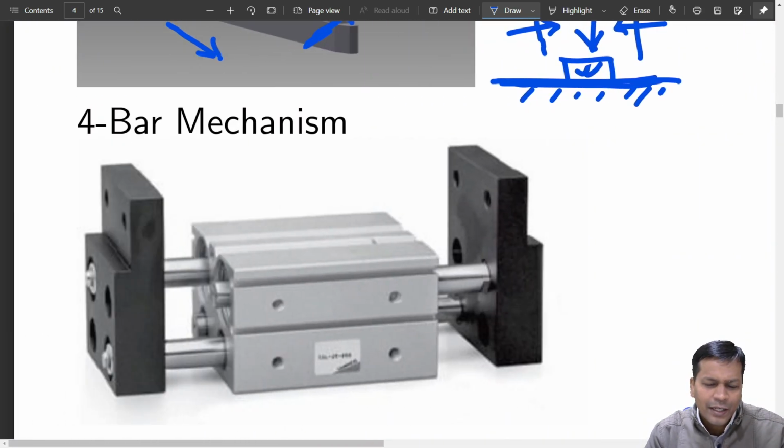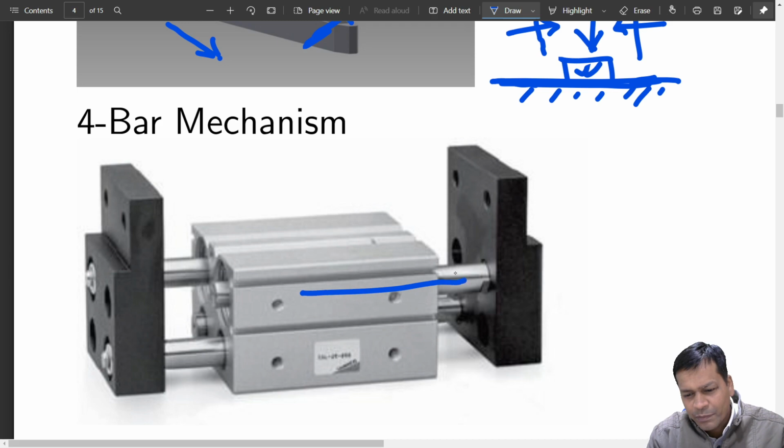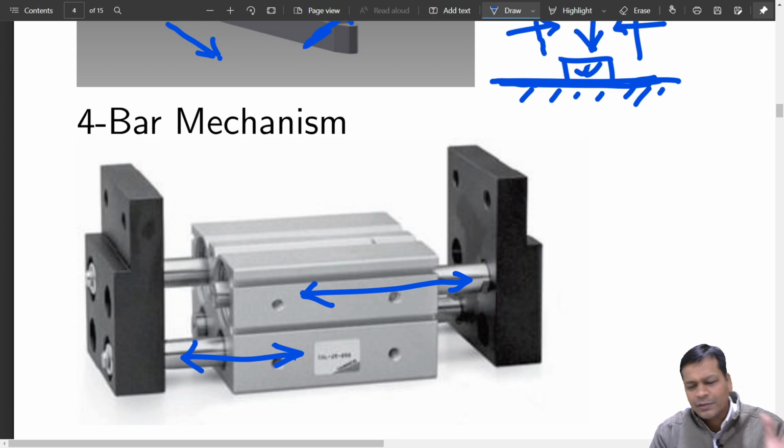And then there is the twin cylinder arrangement. Okay, so you have a pneumatic cylinder which makes this actuator go in and out, and there is another one also, two cylinders doing this job. But yes, both the travels may be a little different. You cannot guarantee that both of them will travel the same amount of distance. If this faces more resistance, definitely this will travel less.